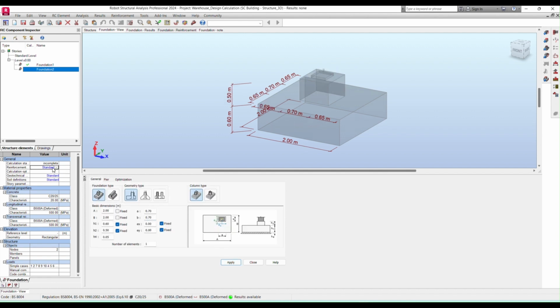So here we simply need to select demo in all the areas. We have no need to go to the right-hand side as we have defined, because that is the structural parameter for the entire building foundation. Wherever the foundation is going to be located, that entire area will be the same, more common, and all the foundation parameters are the same for all the foundations. Only the sizes and the loads differ.